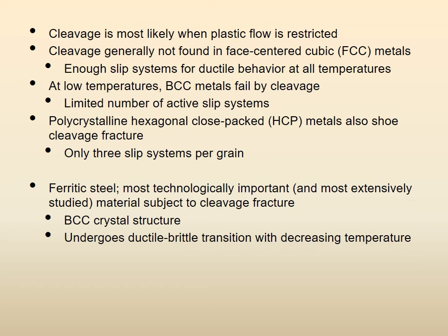this cleavage happens. In polycrystalline hexagonal close-packed, remember that 90% or more of the metals are FCC, BCC or HCP, right? So that you remember. So we have talked of FCC, which generally fails only by ductile behavior, BCC, where a lot of cleavage can happen. Now HCP, they also show cleavage fracture.